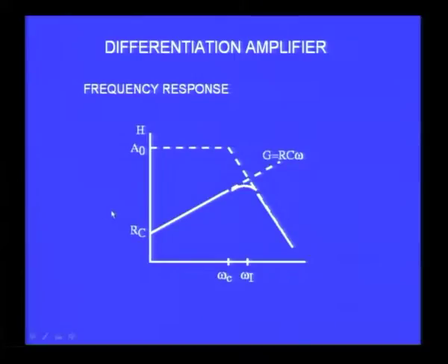Right. So, if you look at the frequency response curve, you would find it will be something like this. It is because it is a superposition of two curves. One is due to the op amp, about which I have not yet discussed, but I will discuss in some detail later on. You have a constant gain up to some frequency, and then it rolls off with a constant slope at the end due to the internal capacitance and things like that, and therefore this is the bandwidth graph, or the Bode plot, corresponding to the op amp, and this is the response of the RC circuit that I have.